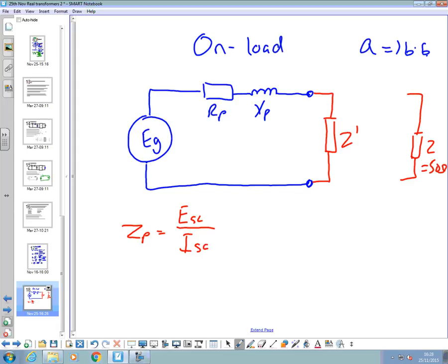That's the total impedance connected to this transformer, at least the magnitude of it, from 69,000 over, no, hang on, not 69,000, 26,000 was the applied short circuit voltage over 4 amps. I made that 650 ohms. Everyone get that far? No? So all you had to do was follow the example short circuit test there.